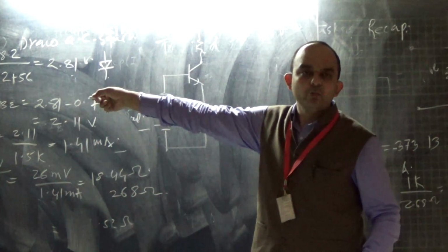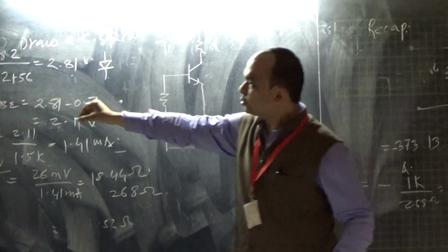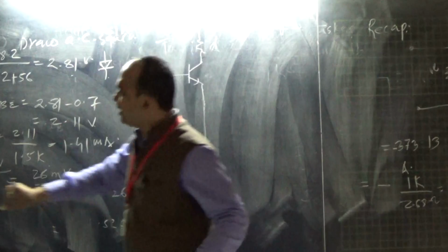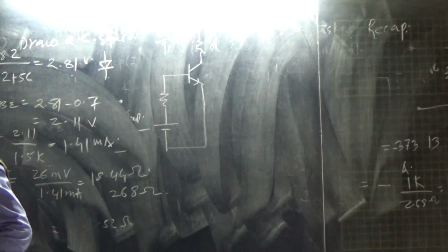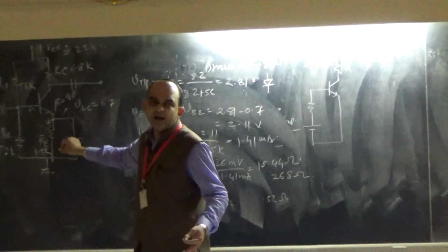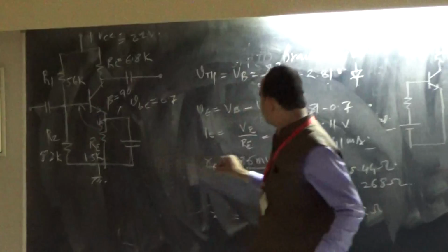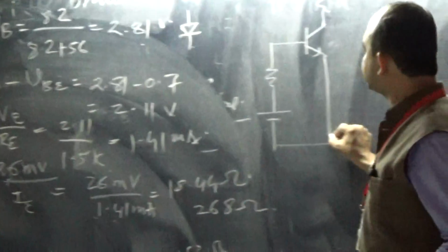Because when AC is applied, capacitor acts as a short circuit. So for AC, now here there is a short circuit, and here there is a resistor. Which path will current flow with less resistance? This is short. So the equivalent of this becomes short.